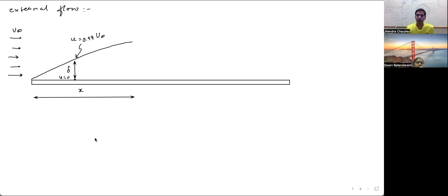Then at a particular distance x, the laminar property of the fluid gets disturbed. What is laminar property? The laminar property is wherein not a single particle of a layer goes below its layer. They always maintain their particular lane of flow and will not descend. The layer below will not change its lane, and the layer above will also not change its lane. That is laminar flow.